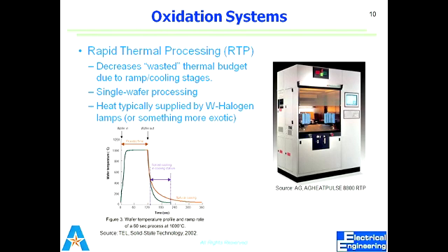At the same time, your oxidation rate increases, because you can heat it up to high temperature in a few seconds. At high temperature, the oxidation rate actually increases. We talked about yesterday that at high temperature, the oxidation rate increases. So that's why this RTP has got a benefit over the vertical furnace. Now, one thing is that it processes a single wafer at one time.